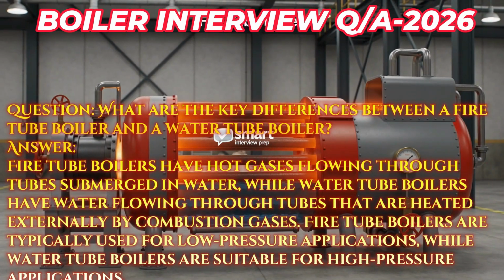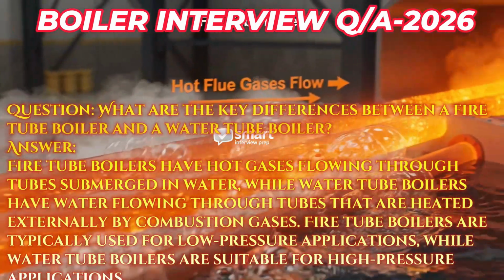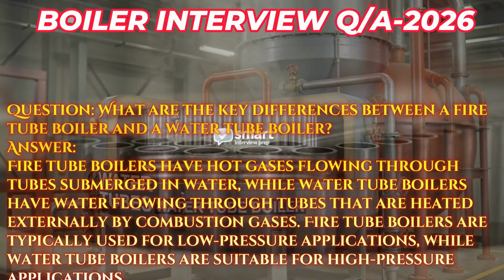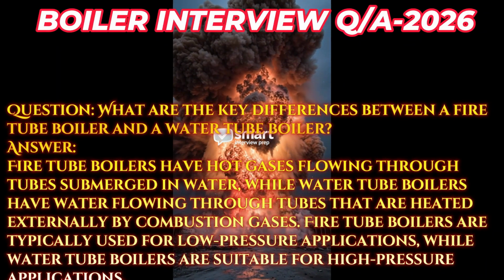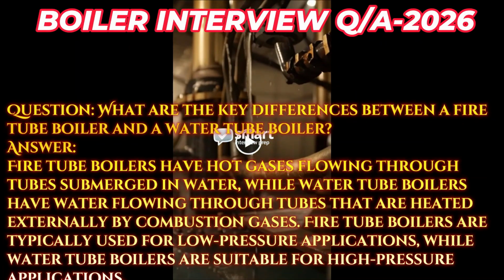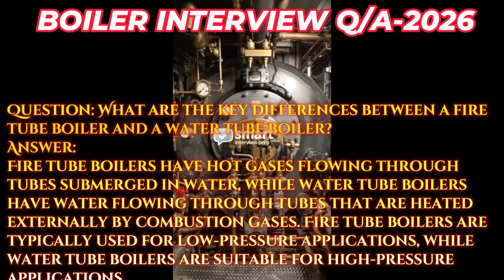Question: what are the key differences between a fire tube boiler and a water tube boiler? Answer: fire tube boilers have hot gases flowing through tubes submerged in water, while water tube boilers have water flowing through tubes that are heated externally by combustion gases. Fire tube boilers are typically used for low-pressure applications, while water tube boilers are suitable for high-pressure applications.